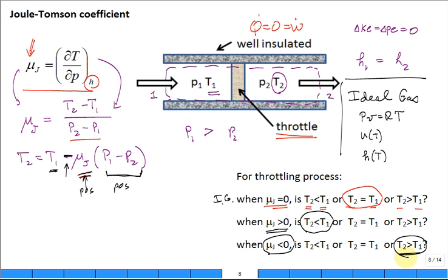This is one of these crazy cases where, hey, some fluid, you go through a throttling valve, no change in temperature. Go through a throttling valve for some, it's really cold. Go through a throttling valve for some, it can be warm. And you know what? For the same fluid, we're going to talk about nitrogen now, okay? We'll get all three behaviors the same.